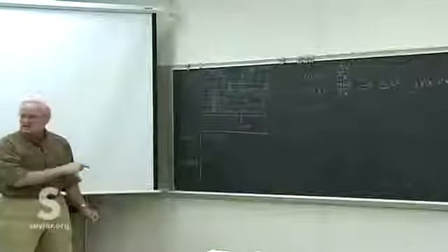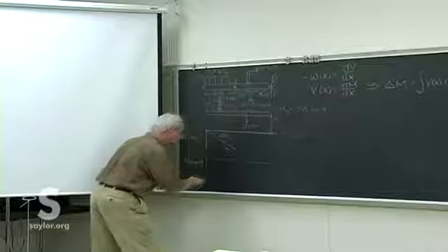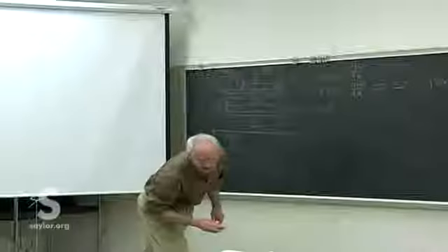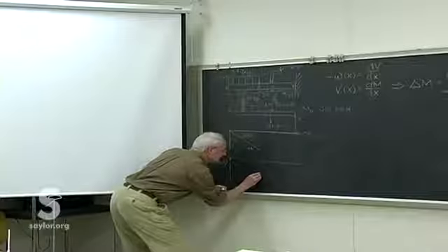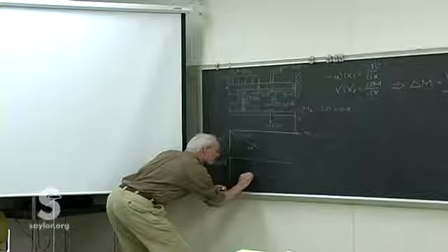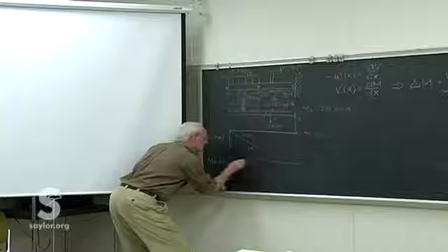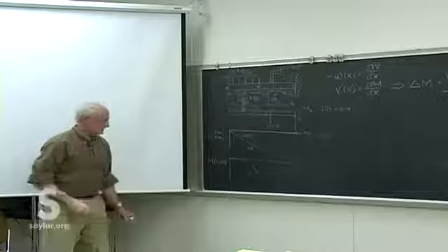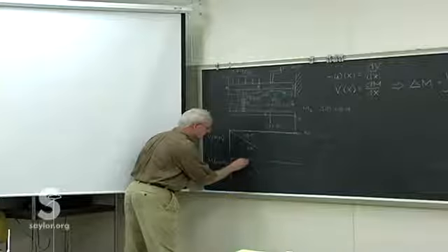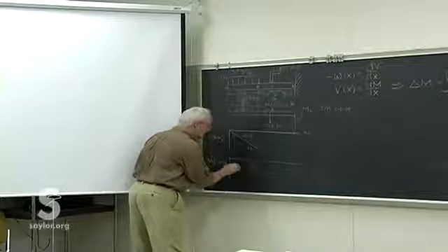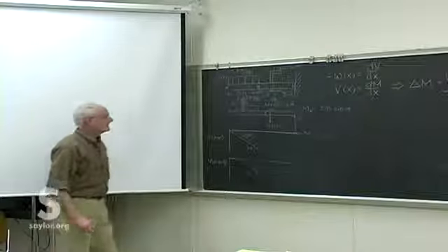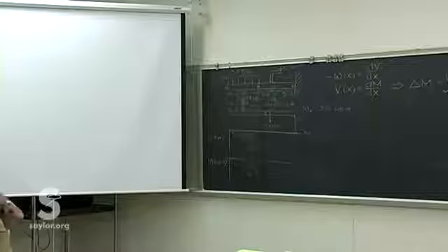What's 4 times? Is that 96? So we know we go down to a minus 96. Let me leave myself enough room. We're going to have to go a little bit deeper later. And then we can draw in the parabola like that easily once we have those 2 points. We know it's at 0. We know the slope is at 0 as it comes in because the slope goes down to 0 as V goes down to 0 coming into that end.